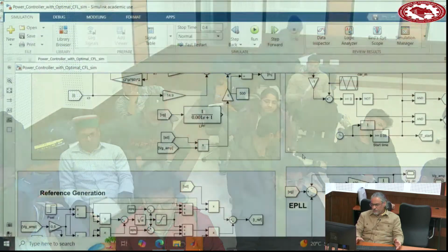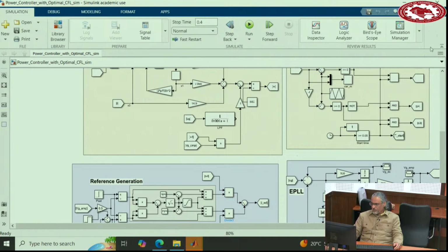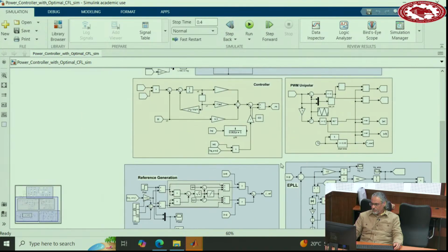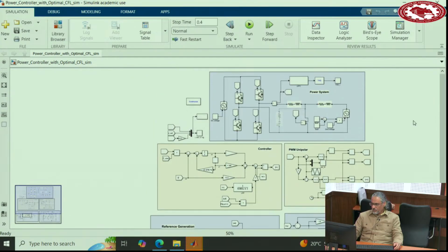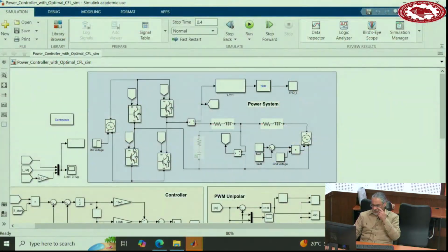Let me explain the simulation file also very quickly. So this is the power circuit here. Again, a full bridge voltage source converter. Here we have a DC voltage. We use controllable because we want to change that. We apply disturbances, even though I don't know if it did here. On the right side, we have one inductor and then one grid. You may want to add impedance here for the grid as well to make it more practical situation. And then this current you measure.